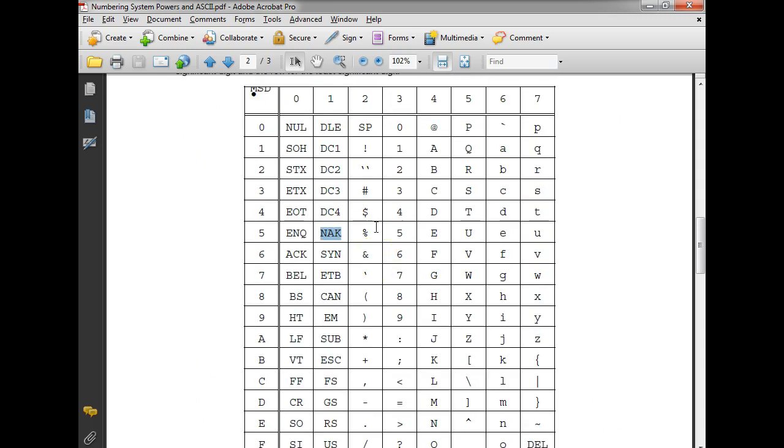If it's already odd, then the parity bit would be 0, right? If the number of ones is a 1, then, not in the data, not the parity bit. So the receiver counts all the bits, including the parity bit. And then it throws the parity bit away, because that's not what I'm sending when I send the letter A.